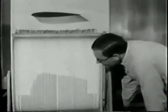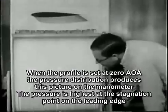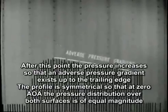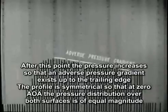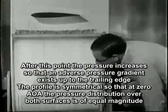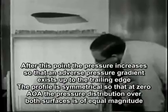When the profile is set at 0 angle of attack, the pressure distribution produces this picture on the manometer. The pressure is highest at the stagnation point on the leading edge, but decreases as the air flows aft until a minimum is reached near the point of maximum thickness. After this point, the pressure increases so that an adverse gradient exists up to the trailing edge. The profile is symmetrical, so that at 0 angle of attack, the pressure distribution over both surfaces is of equal magnitude.